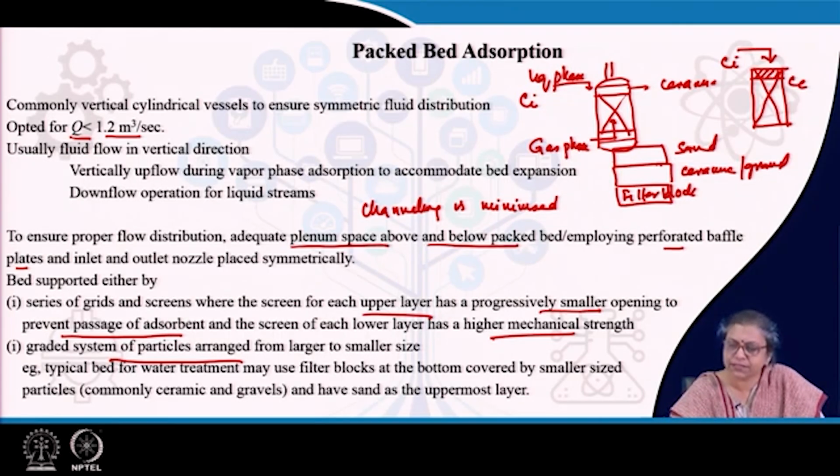So, after this, the fluid which is flowing is relatively free of the adsorbed component. The material which has to be adsorbed gets adsorbed within a thin layer at the beginning, and after that the fluid, relatively free from the adsorbate, flows down and exits the adsorber column. So, the effluent that comes out is relatively free of the adsorbed substance, correct.